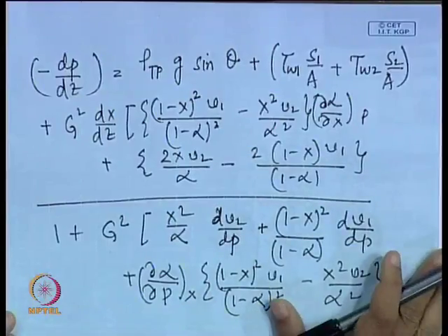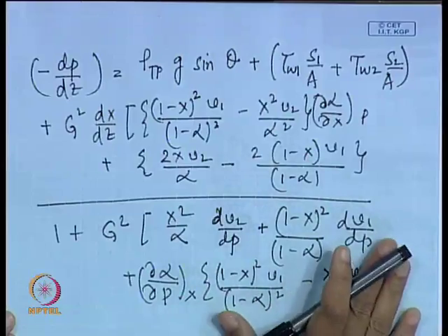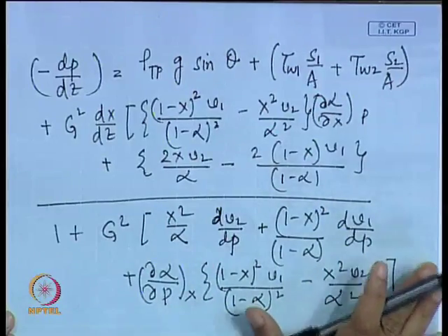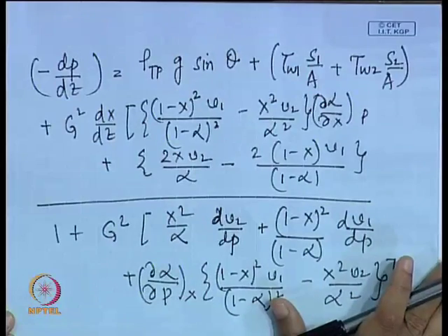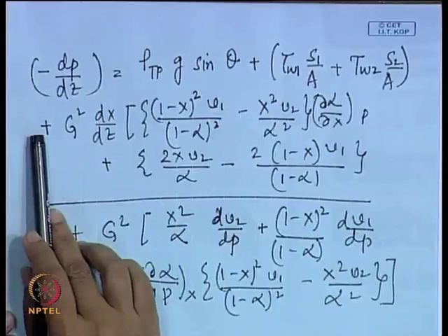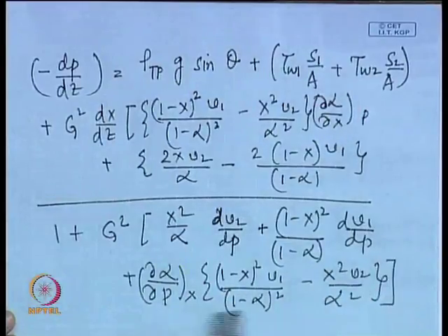Now, after that, if you see what we have done, our intention is simply to predict the pressure drop for two phase flow under separated flow conditions. This is our intention. For that we wrote down the momentum equations, and then we combined them to find the mixture momentum equation, and the final expression we have got is this particular whole equation, which enables us to calculate pressure gradient from known input parameters.